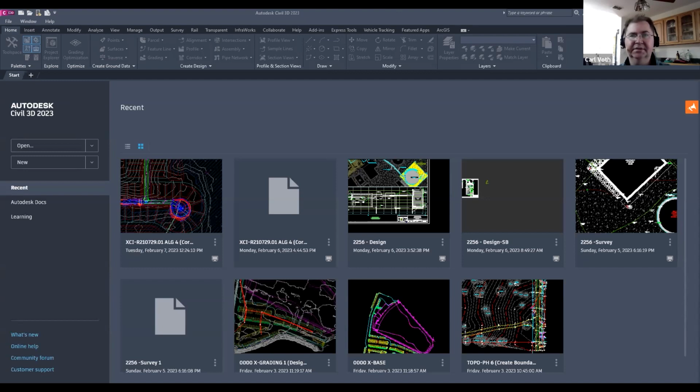And then we're just going to go through and individually select some of these that we need to pull from. So go through and hit OK. And now it's going to tell me that I've got 4 baselines and 10 regions in my road A1 and my road A2. Process those out.